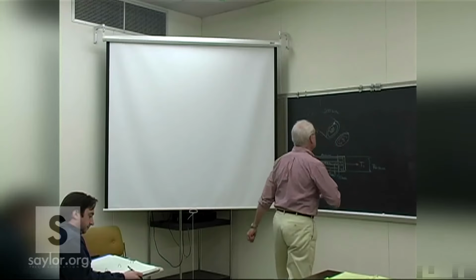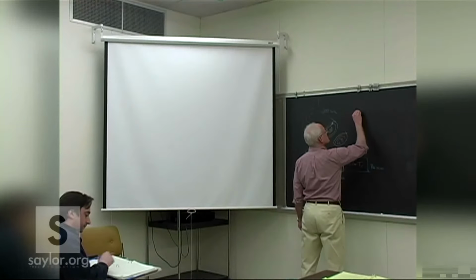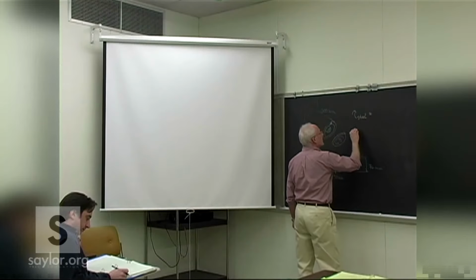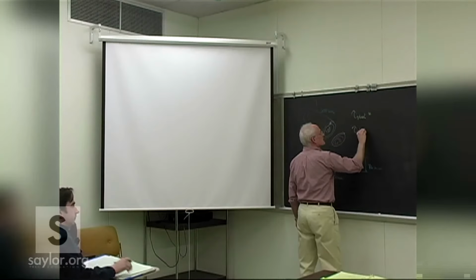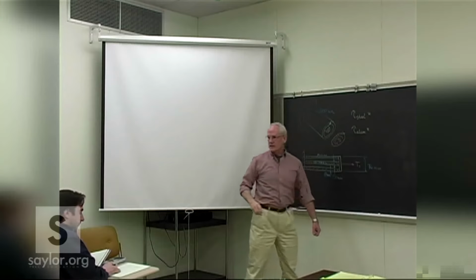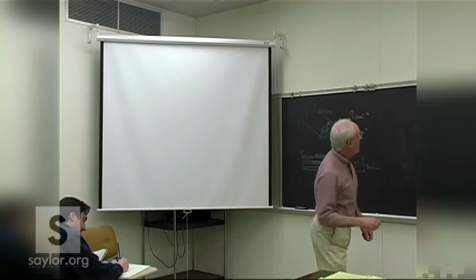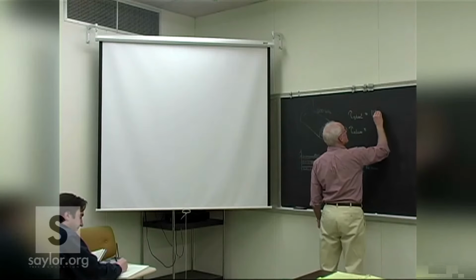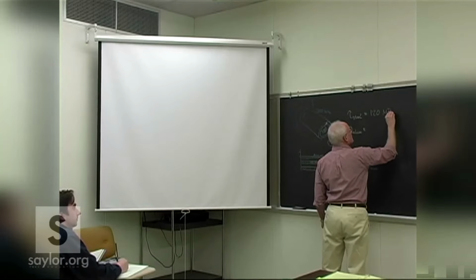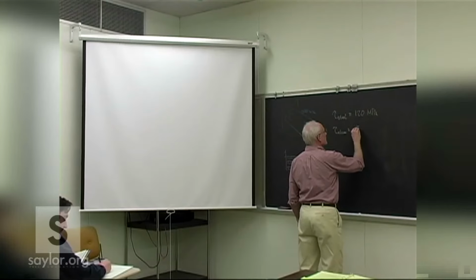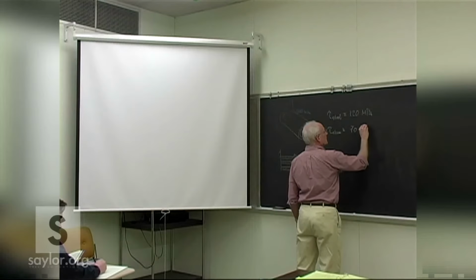All right, some of the material limits with which we must stay below. We have an allowable shear stress on the tube, and we need to stay under both of those. 120 megapascals for the steel, 70 for the aluminum.